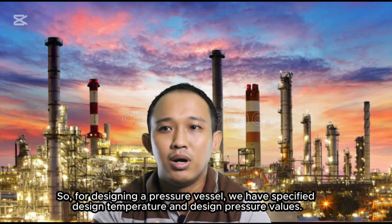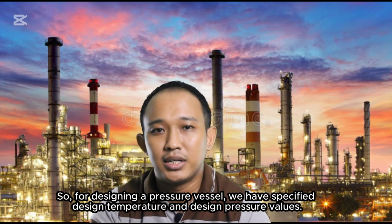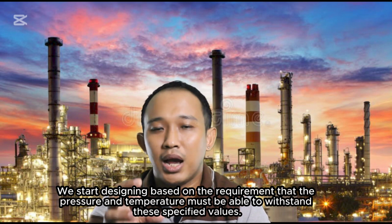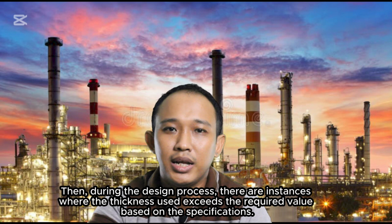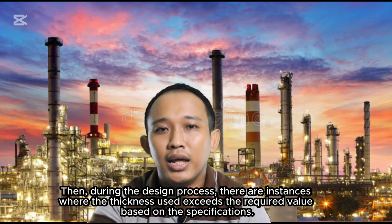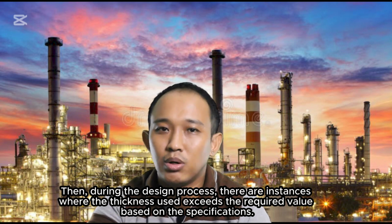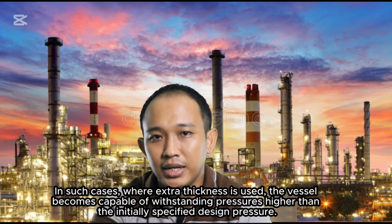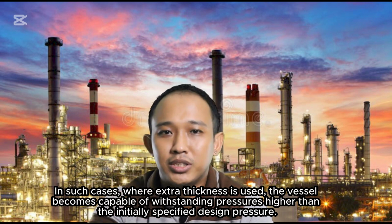So, for designing a pressure vessel, we have specified design temperature and design pressure values. We start designing based on the requirement that the vessel must be able to withstand these specified values. Then, during the design process, there are instances where the thickness used exceeds the required value based on the specifications. In such cases, where extra thickness is used, the vessel becomes capable of withstanding pressures higher than the initially specified design pressure.